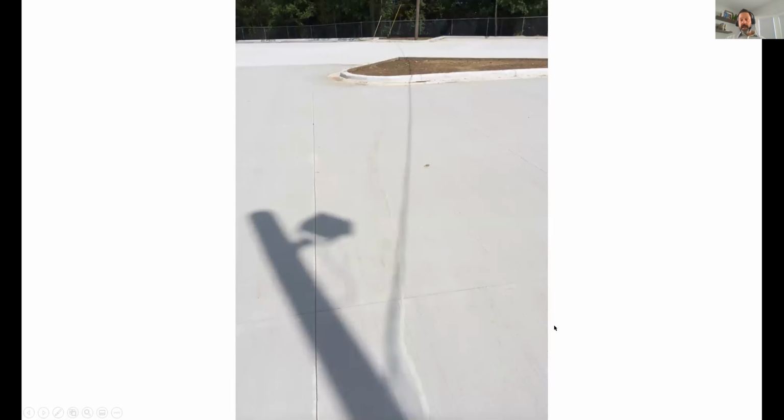Here's one. This is actually that parking lot in Jackson that Heather mentioned, where they didn't do any cuts and came back the next morning, and this crack had been in there at the weakest point, which was the narrowest point in between the island and a walkway on the other side. So essentially that initial relief cut was actually a crack. They came in and then epoxied that one. And then the rest of the saw cuts were placed in the next phase at a proper time.